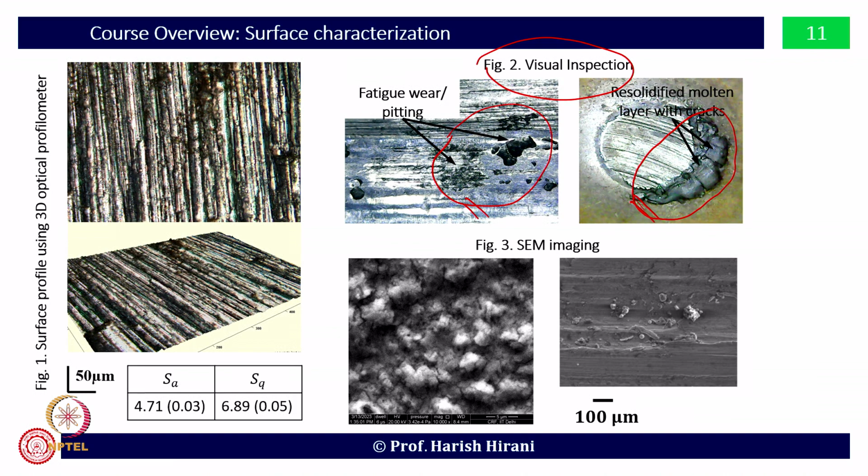But we are not interested only in this, because we want to figure out what the root cause will be. Now, if I enlarge this portion, I find a very high surface roughness over here. You can see the peaks and valleys, and these bring a lot of discontinuity, and they also leave a lot of room for wear phenomena. Now, if there is water content or some weathering condition available, this will enhance the wear rate much faster. Even if there is some sort of acid, it will increase the wear rates significantly. So, these are the important aspects to look at.